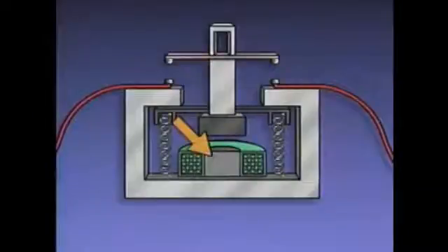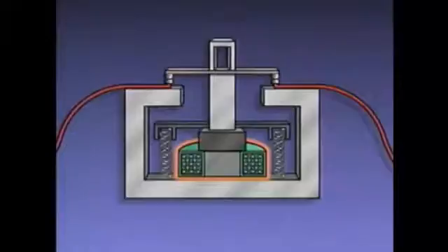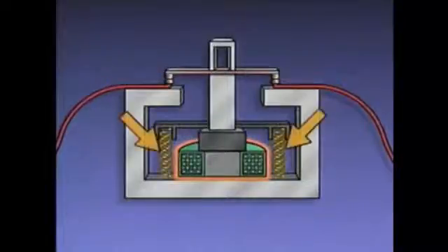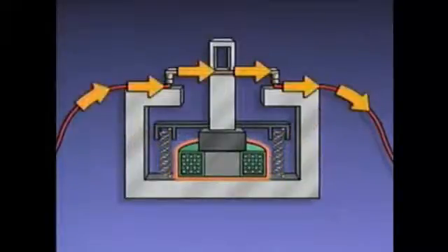An iron core inside the M coil concentrates the magnetic field. When the M coil is energized, it becomes an electromagnet and attracts an armature. This moves a set of movable contacts against a set of stationary contacts. The armature is connected to a pair of springs, which are compressed as the armature is pulled down. When the contacts close, a complete path for current flow is established through the controller to the motor.